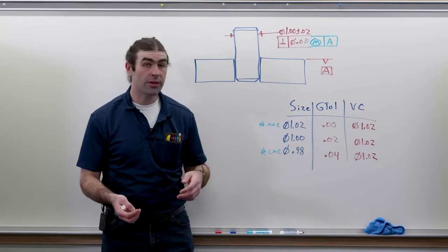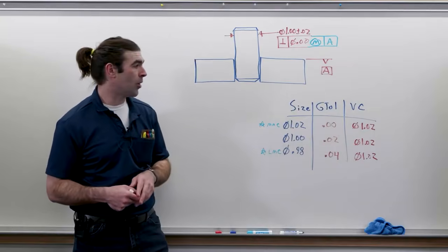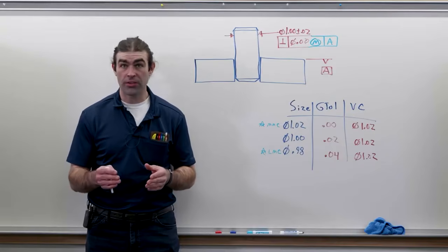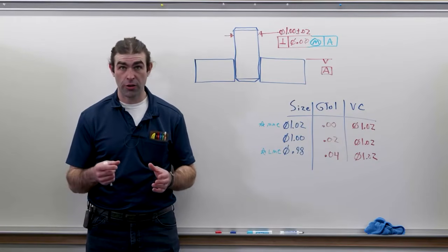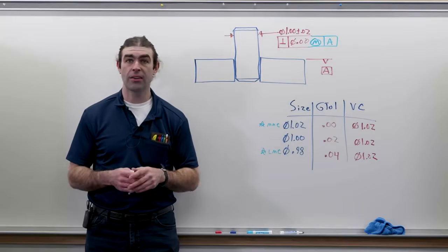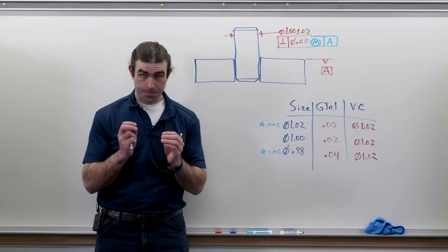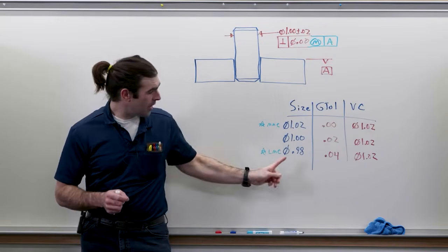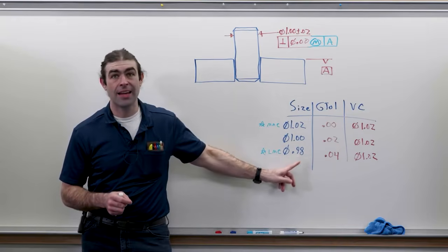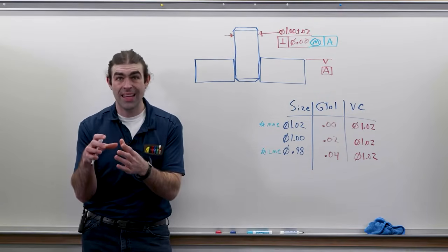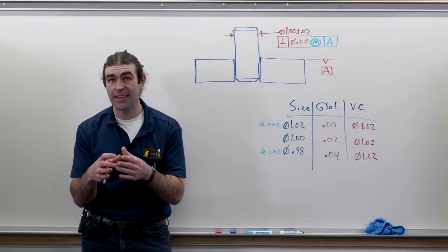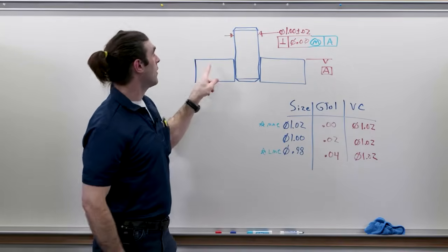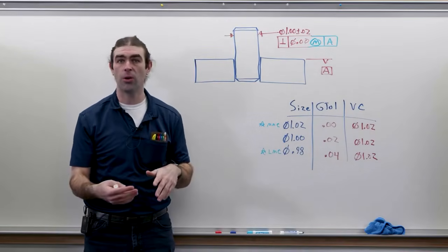You also get a virtual condition with this, which is going to be a little bit smaller, right? So 1.02 for this feature. That would be the diameter, the smallest diameter of a mating part that would fit over the pin and make full contact with datum A. Now, if you had a mating part that was smaller than the virtual condition, say 0.98, it might fit over the pin, but it might not make full contact with the datum, right? You imagine this pin is crooked and you try to fit something on there, it's going to touch one portion of this, not the whole thing.